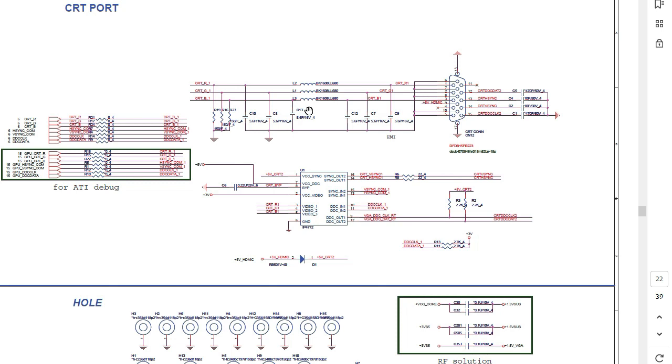Based on my experience, the most common fault for this kind of connector is when an inductor here is cut. So if you have a problem with this connector, you should check these 3 inductors. First select the continuity option on the multimeter, then check each inductor. You should get a very low resistance or a buzzer.